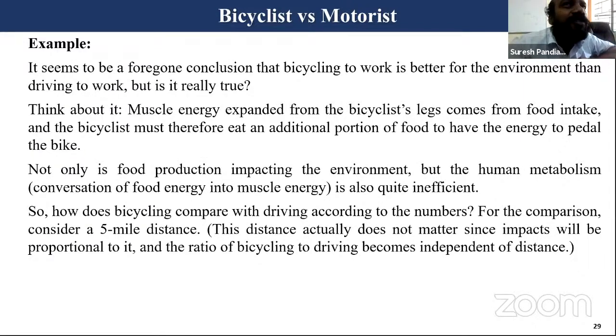Introduction of the metro rail system. Why do they expand it, a 10 kilometer stretch, then 20, 30, 40? Because the metro system gives less carbon emission per passenger kilometer travelled than the bus or other modes of transport. If you go by personal vehicle, or in a bus, or in a metro, obviously in the metro your emission is less. How? Because metros use electricity, so the emission occurs where you are procuring the electricity.